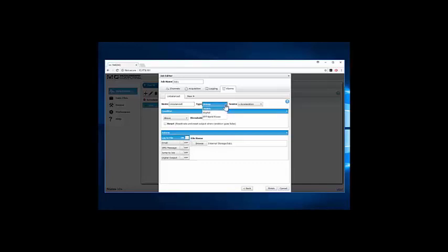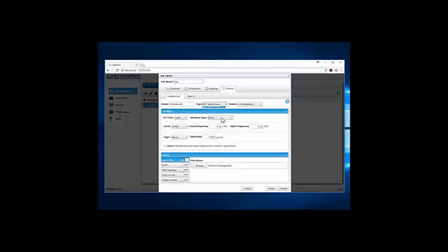You can create an alarm based on an analog or digital channel, or you can also alarm based on FFT band power for this particular device. You can set up the FFT size you want to check for your alarm condition, any window function, based on in-band or out-of-band frequencies, and set the power threshold for your alarm condition.